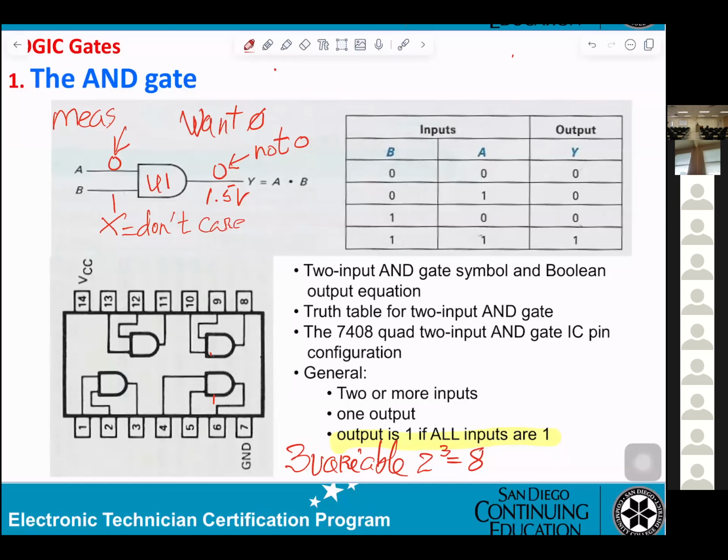the supervisor will be asking you, why do you want to change U1? And you say, okay, I want the output to be 0. However, it is not 0. I take the input at A, I get 0. Okay? Then the output must be 0. If it's not, that means the IC is not working.